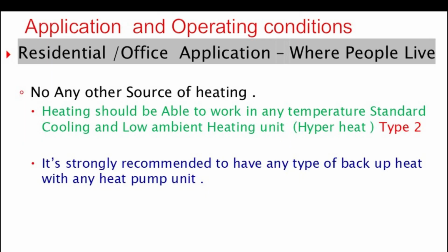The second application I'd like to discuss involves the same residential or office setting, but with no other heat source available. In this case, you'll need a heat pump to provide primary heating throughout the winter. However, one key challenge with heat pumps is that they lose capacity as outdoor temperatures drop. Therefore, it's crucial to choose a heat pump that performs well in colder conditions.